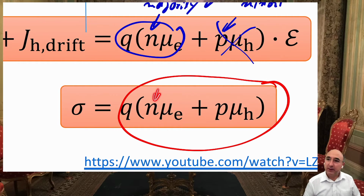And some of you have told me if we increase the doping, we can increase the conductivity because we increase the number of electrons, for instance. And I say, if you increase the number of electrons, you increase the disturbance. Why? Each phosphorus atom is a phosphorus ion. It is charged once positive because it has donated one electron. So if you have now an electron moving around, it is attracted. So this attraction, the scattering, reduces the mobility.